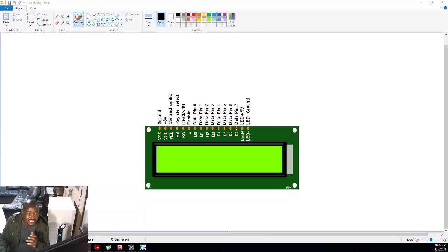Now, this helps you so that instead of using 8 bits on your PIC microcontroller, you get to save 4 of them. Let's say maybe in your applications you need extra pins to do controls on other things. You will have 4 data lines freed for other purposes. You will interface the LCD only with data line 4 up to data line 7. Now, you still need to send 8-bit data to the LCD, but using only 4 pins.